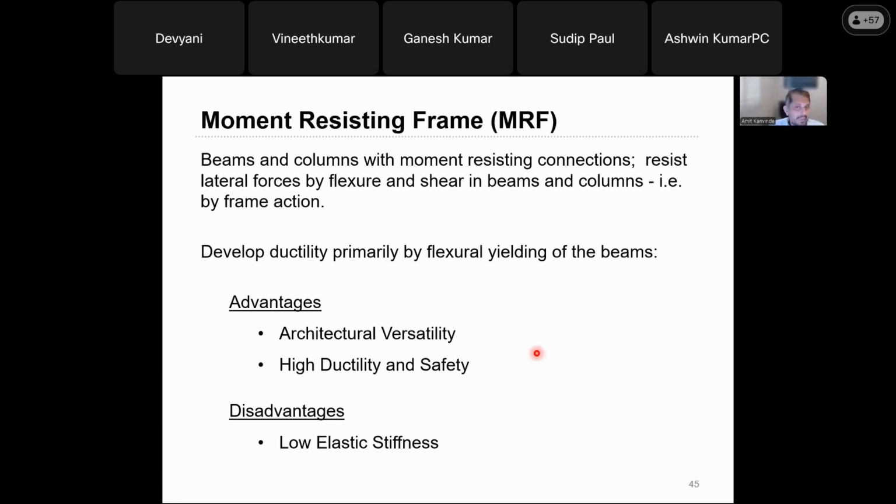So now when we're talking about developing ductile behavior in moment resisting frames. Remember, moment resisting frames have an R factor of 8, which means we want these frames to ride that plateau for a very long time. And the reason we want them to ride that plateau for a very long time is because they're actually getting designed for a really, really low load relative to the elastic response spectrum load, like 1/8 of that load, right?